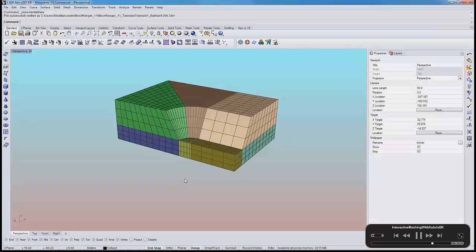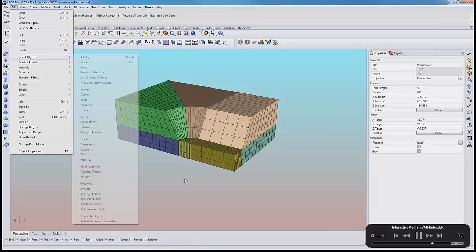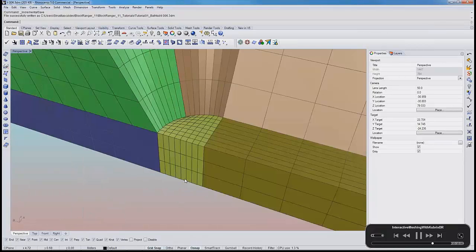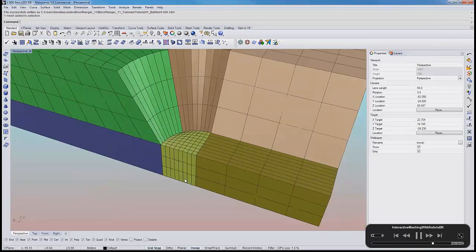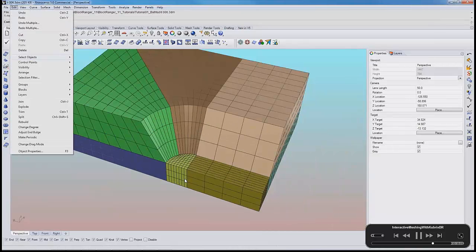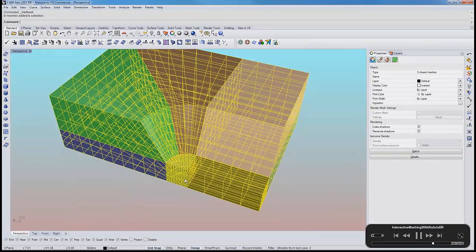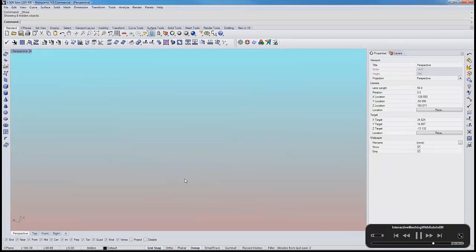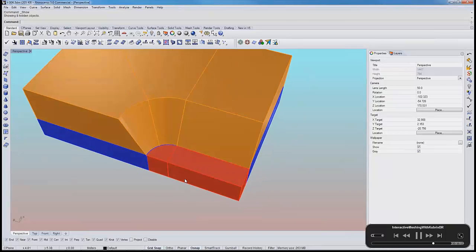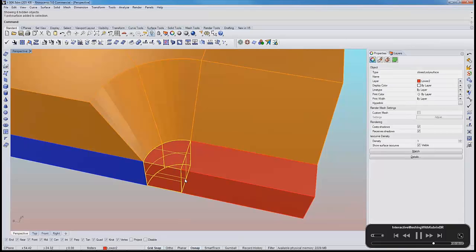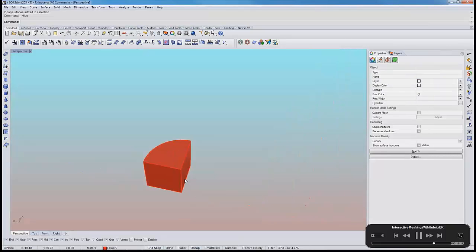So what we're going to do is take that quarter cylinder solid and split it in 2, as opposed to this one single quarter cylinder. So we will create 2/8 of a cylinder. You will see that here. First, we select the solid in question, which is this one. We hide everything else but that.